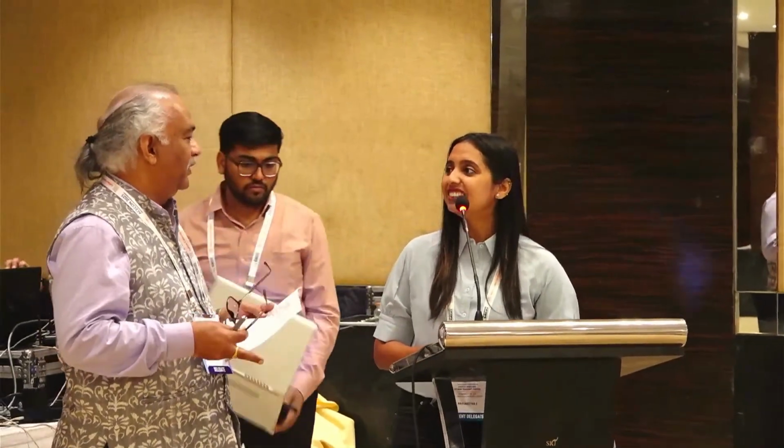That we are facing the workability issue. Yes, sir. Still, here I haven't presented. Yes. So actually, as I mentioned, the coarse fibrous particles will absorb more water. That is very porous, so we have to remove that. Then we will get a little bit better workability compared to that. Instead of using raw bagasse, we have to process it. So we have to use the superplasticizer. I've used it. I have done the rheological part also, sir.